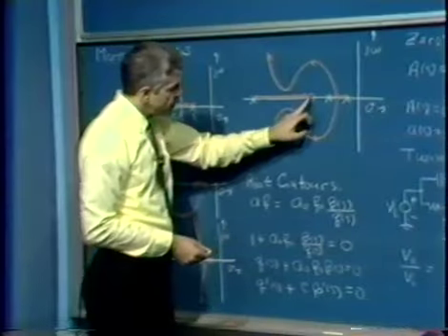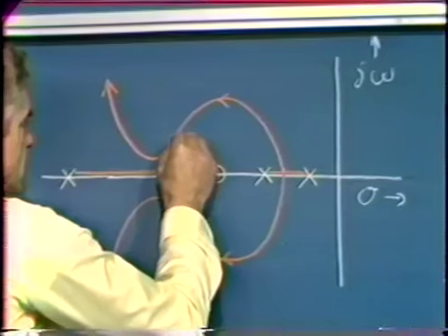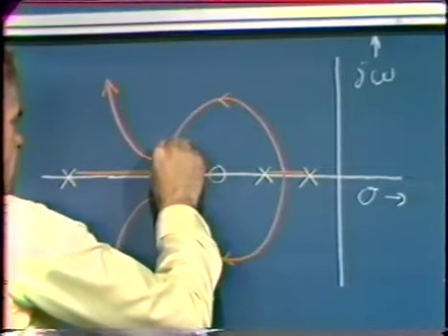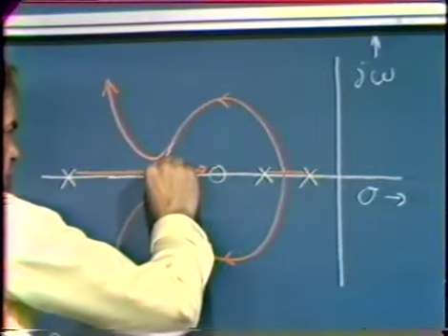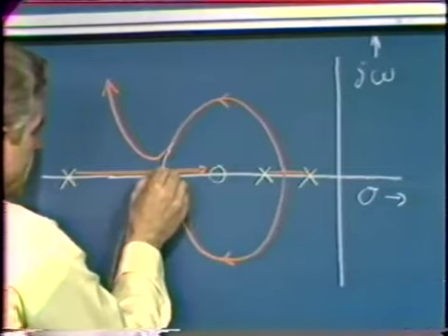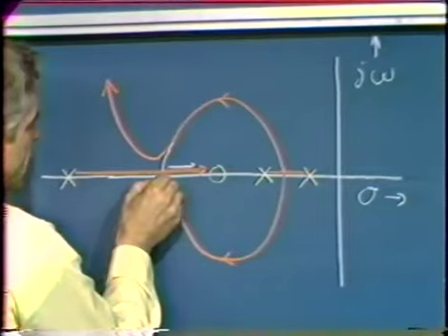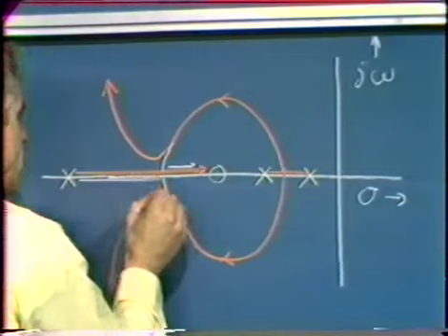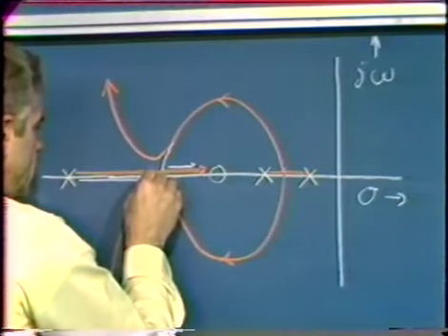Now let's move this zero just a little bit further in. And then what happens is that the branches come down like so. They hit the real axis at right angles, because they always hit the real axis at right angles, and make their way, one of them inward, one out, where it now meets this one. And once again, branch away finally at right angles.